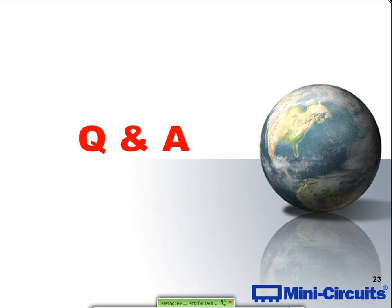Okay. Does Mini-Circuits guarantee an IP3 as a spec? Depends upon the part. For example, we have some very high IP3 parts that we do guarantee in our catalog data sheet what the IP3 is. But one of the things that we can do, and really this is consistent with the type of business that Mini-Circuits does, is we will work with any customer and come up with a custom specification solution. That doesn't mean that we're making a new or unique design for that customer, but if a customer wants us to guarantee IP3, we will work with them, and then we will screen for that IP3 level.